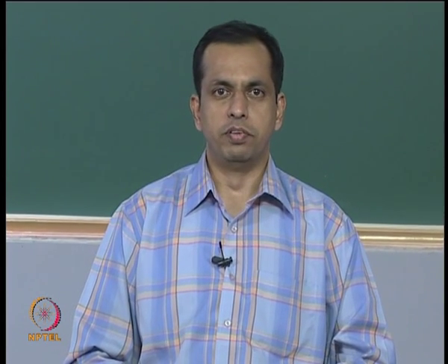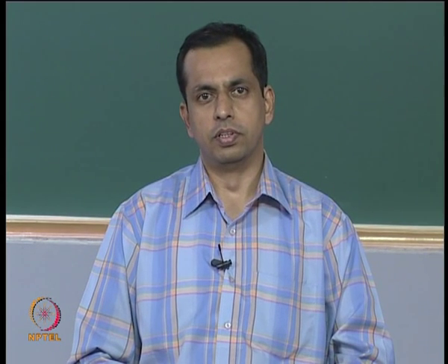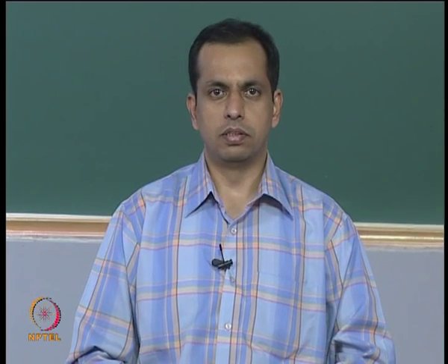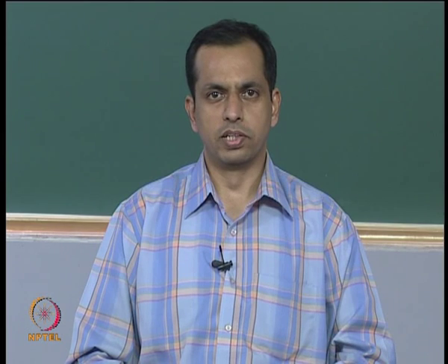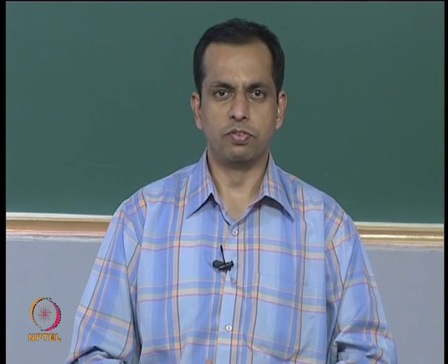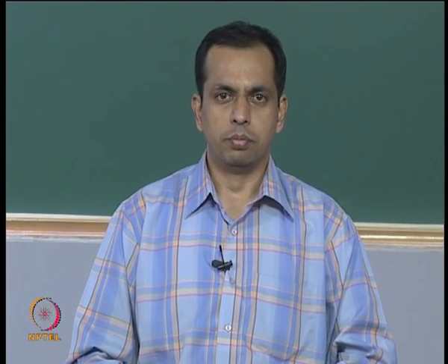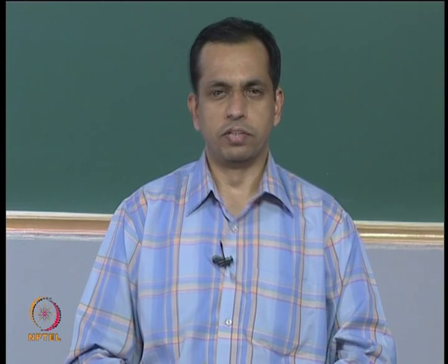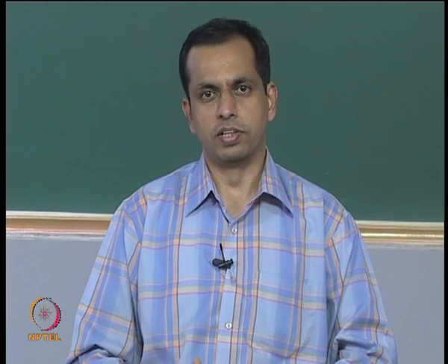Hello everyone and welcome to lecture 40 of analog integrated circuit design. In the previous lecture we looked at the advantages of fully differential circuits, that is where every signal is carried on two wires and the two wires carry equal and opposite voltages with respect to ground. The main advantage is immunity to interference as well as that they cause less interference.